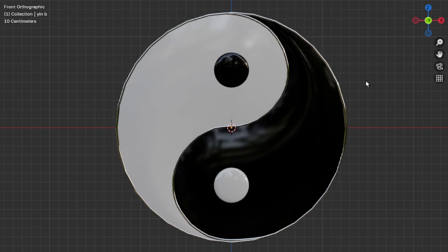So in this exercise, what we saw is we created a circle using the reference image. So we learned how to load a reference image, and in the outliner how to name all these objects. Then we used mesh to curve conversions, and then we applied emboss effect using the proportional editing option. Then we applied material properties, and we brought some shining surface and reflections to the shape.